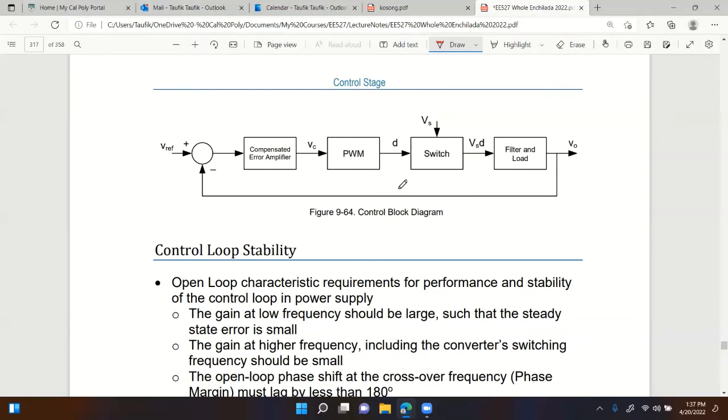Of course, if you have the gain on the feedback, that gain would be a fraction, right? A fraction of the output voltage. So therefore, the VREF would also be sized based on the fraction of the voltage we want to compare with, right? So if that fraction gives us 1 volt, then the VREF would also be 1 volt, and so on and so forth, right? And again, as you saw last week, or actually on Monday, this VREF is internal to the controller, right?